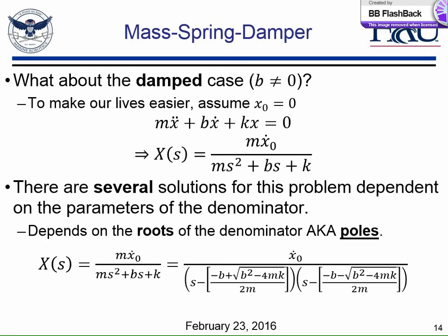So we get the bottom equation. What happens here is that we're big boys now. We can deal with imaginary numbers. So now we get several solutions that are possible depending on the value of b squared and 4mk. If b squared is greater than 4mk, we're good, we're in the clear. We're back to 7th grade algebra. B squared is equal to 4mk, awesome, even better. The entire radical drops out, we have to deal with just the square, with some kind of polynomial that's raised to an order. But if b squared is less than 4mk, we have to deal with imaginary numbers.